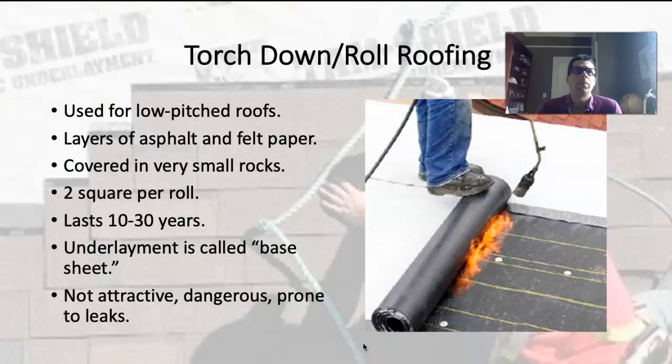And I would just say that it's dangerous, it's hot, people get burned, and then the other thing is people set houses on fire. So you're supposed to do, I think it's a 1-hour fire watch after you're done doing the torch down, to make sure that you didn't catch something on fire and then drive away and the house burns down.